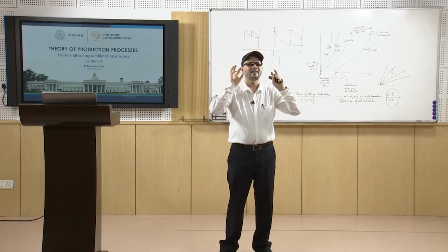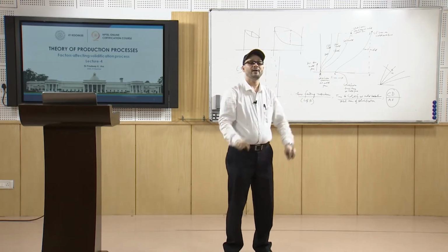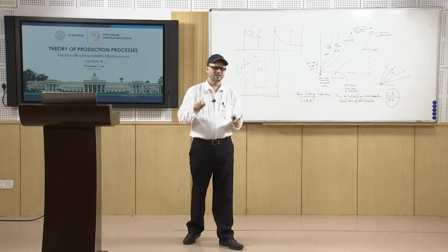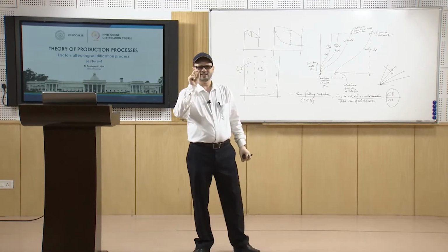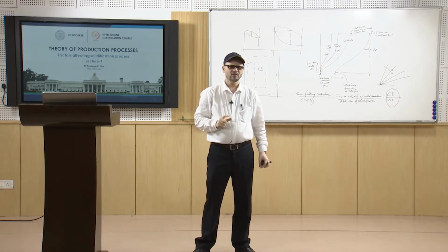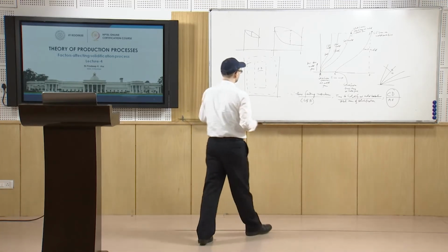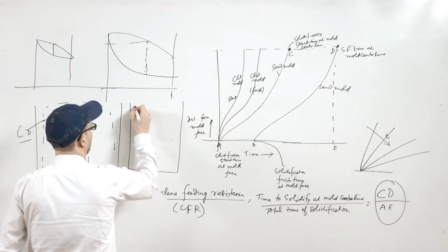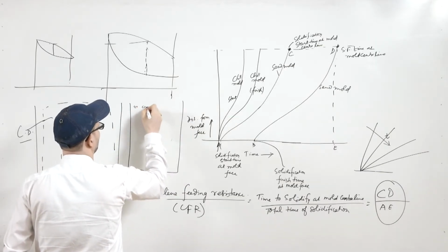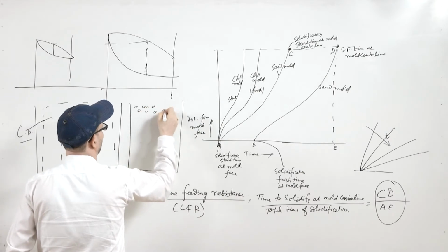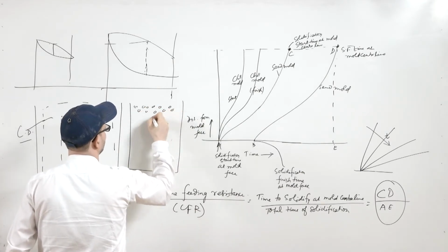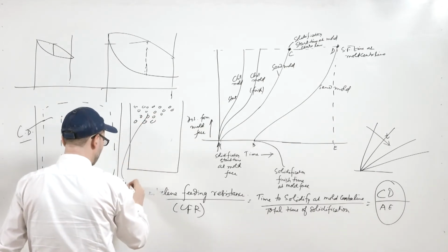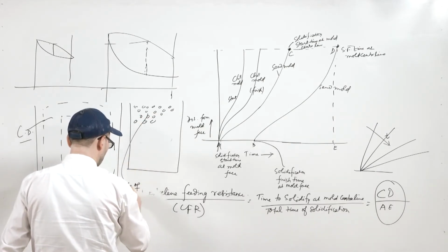Nucleating agents are added into the melt. These nucleating agents or inoculating agents work as independent nucleation centers. So, if you use the nucleating agents, the whole domain will be an equiaxed structure. So, basically this will be because of the use of a nucleating agent.